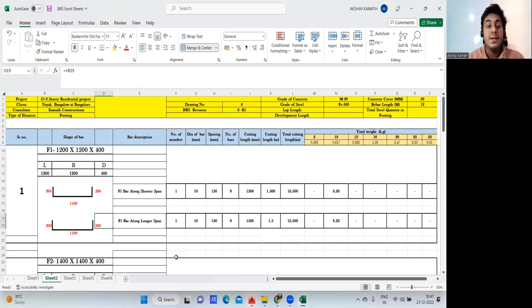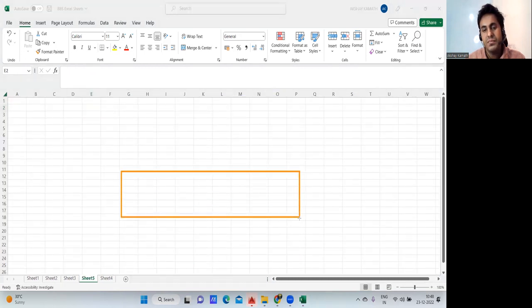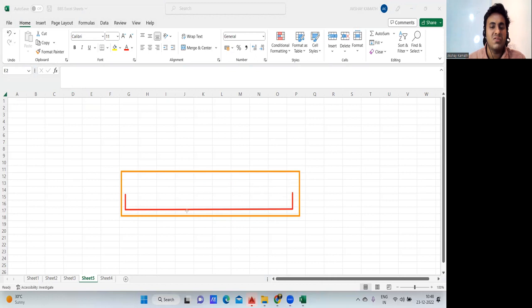I have seen people doing both, but most of the construction practice is they apply two-third, because of this L. For example, let us say this is my footing, I'll explain here. Whatever L you are putting, this top will come in this way. I'll go with only bottom reinforcement, no need of top. This much it will come. Only up to this much length it is enough, because that itself is your development length.